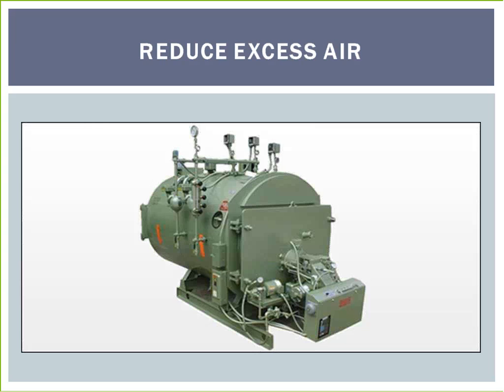Monitoring the flue gas temperature, oxygen content, and carbon dioxide content allows the operator to minimize this cushion and fine-tune the boiler for optimal efficiency under varying ambient and load conditions. Portable or fixed combustion efficiency tests are available from many sources and may be used to manually adjust combustion air quantities. This is typically the only choice for natural draft type boilers and should be performed on a weekly basis. For forced draft boilers, an automatic combustion control system can be added to automatically monitor flue gas combustion and adjust combustion air quantities on an instantaneous basis.